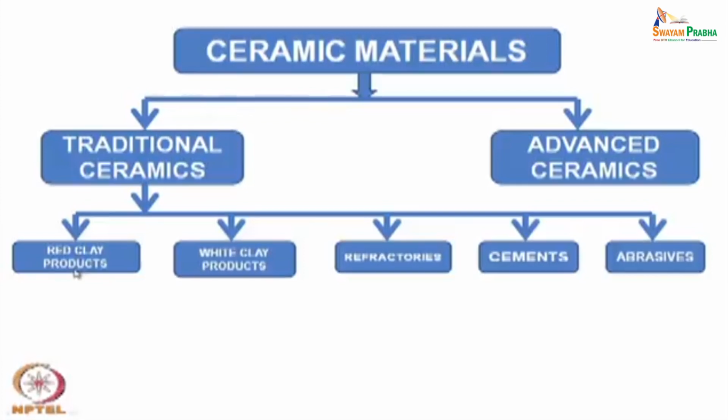We will discuss in a few minutes how exactly the ceramics are prepared. Ceramics basically start with powders as starting materials, and they get consolidated. Then one of the major steps of bringing in strength to ceramic materials is what we call firing, or heating to high temperature.